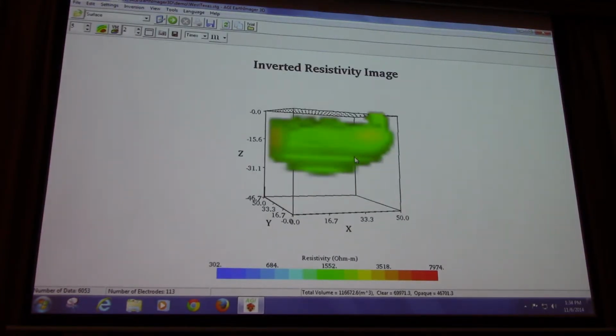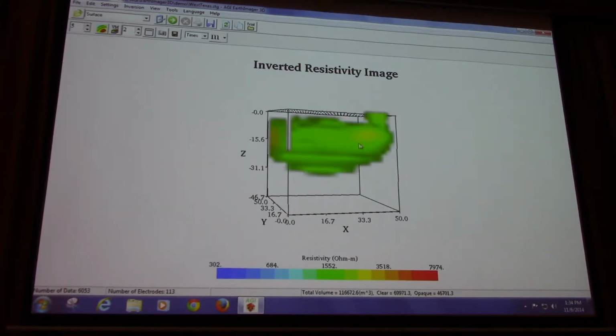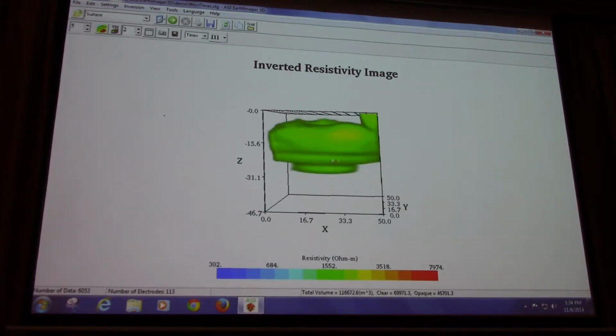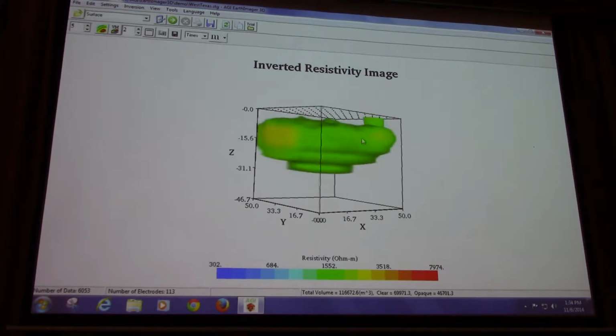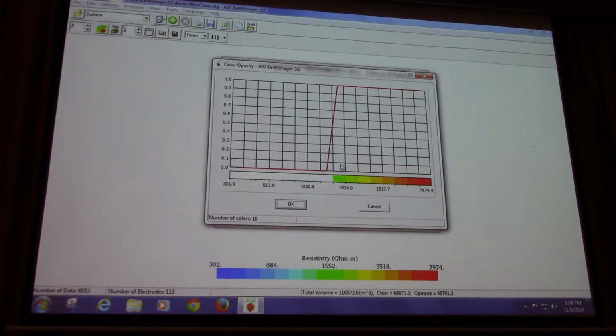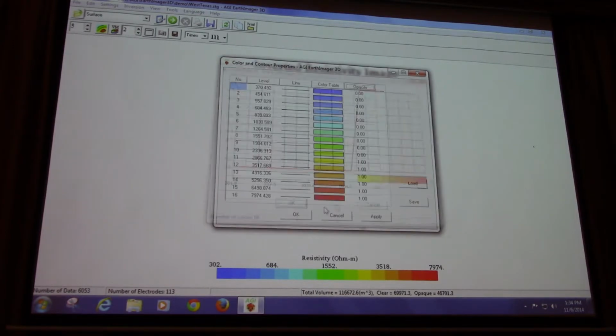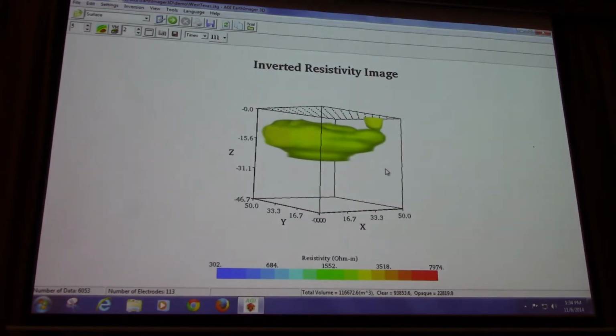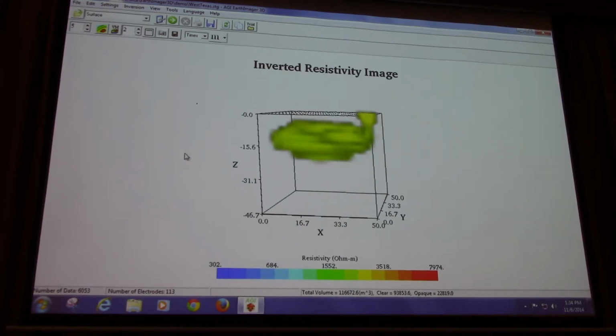Okay, here you actually see the shaft that they dug down. And what this actually is, is a gypsum seam. Gypsum is, well, you know what drywall is, right? That's gypsum. So it's very dry, very resistive, and shows up as very resistive here. Of course, I'm deciding where to draw the contour, and I know it's not that big. After ground truthing, I know that it's actually smaller. So if I maybe go like that, there we go.